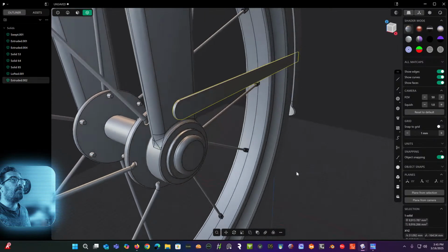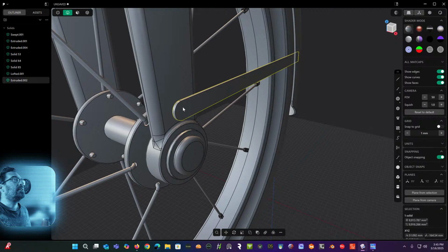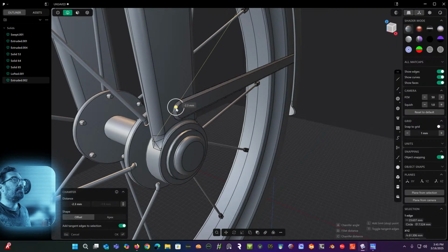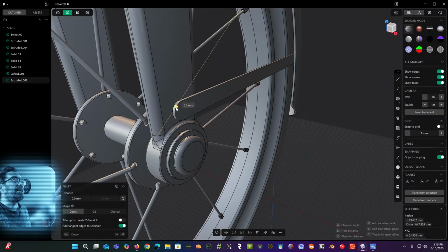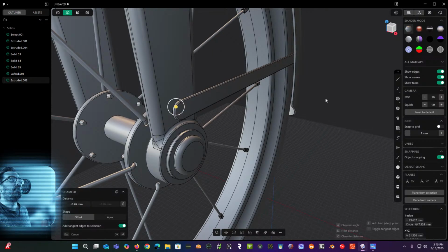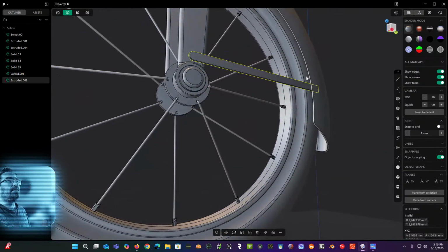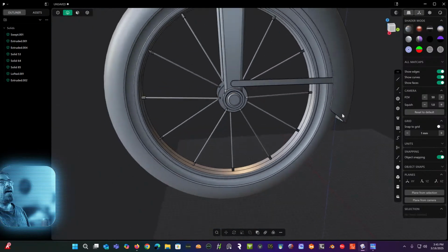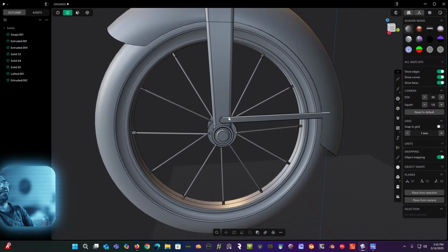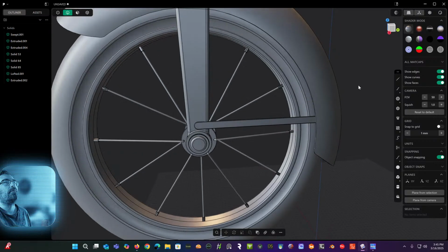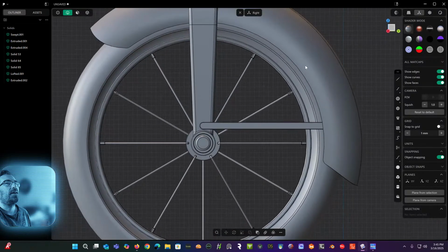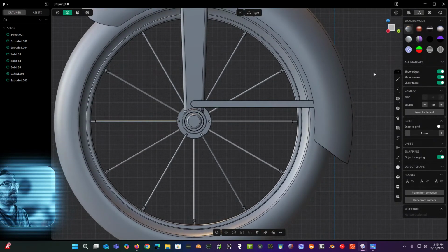Okay, let's just go ahead and grab the edges. Kind of chamfer that in slightly, like maybe at a like there, 0.76, less than a millimeter. And with that, we're going to wind up putting a bolt here, and we're going to make 2 of them. So let's do that first. I'm just going to, and you know what? Let's make it have the same middle section.